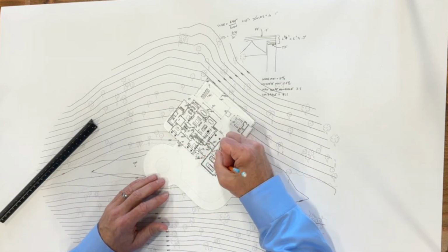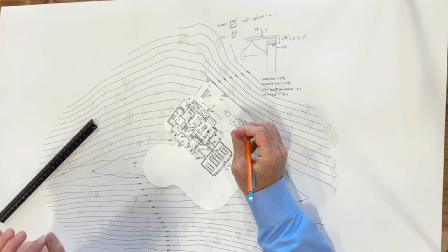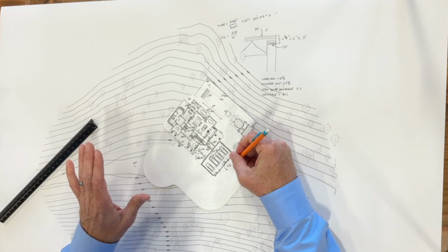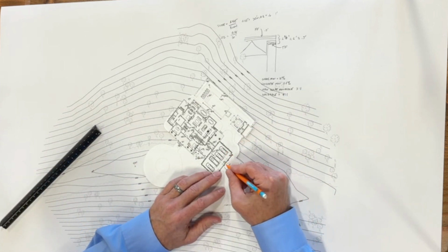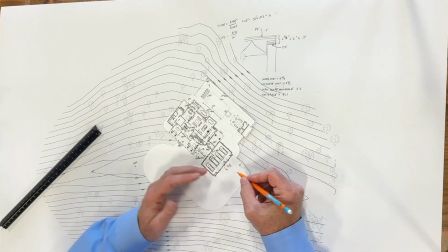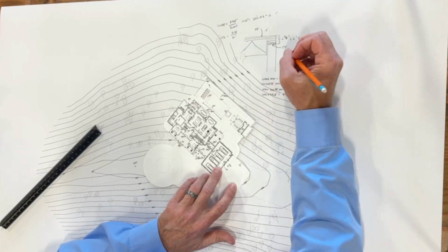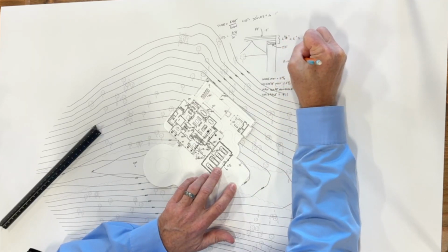So now you got to get the water to drain out this way, again, at a 2% slope minimum. And we don't want this to be too much because if you want to play basketball in your driveway, that's going to be a drag. So what that means is now we want to say, where do I make that next contour line? If it's 941, where do I put the 940, right? So then you're saying, well, how far? That's really the run, right? So the run is equal to the rise divided by the slope.